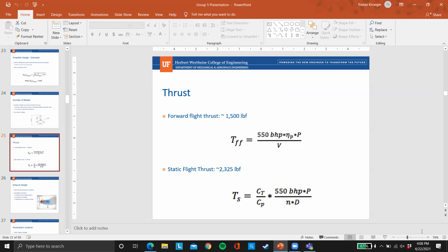If it's in the reasonable range, I would suggest that the thrust weight ratio times the takeoff weight, you put that here, is the thrust required, right? And then we have the thrust generated by your aircraft, and we say, okay, our design satisfies the requirements. Yes, ma'am. So that is that part.